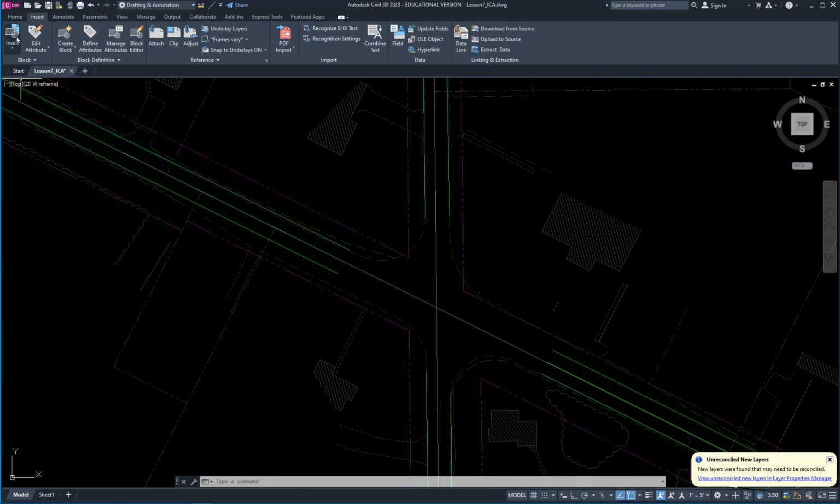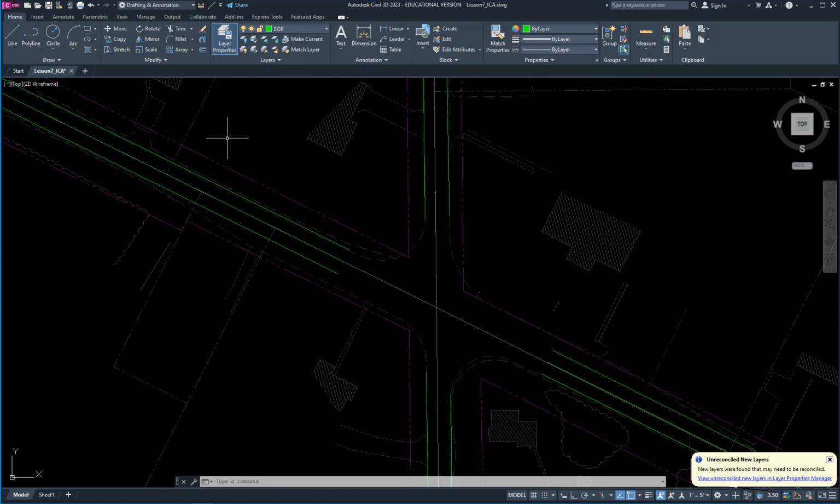And if I go back to my home screen, the easiest way I know to do this is use the fillet command. You can draw arcs in, you can do it yourself, and you can snap to it and keep all your tangents in there. It's kind of hard. Fillet does it all automatically for you, so that's what I usually use. So I'm going to turn that on. I'm going to make sure the trim setting is set to trim. And so I set T for trim, and accept trim, and now I'm going to set the radius.